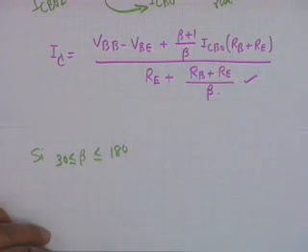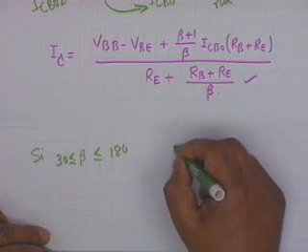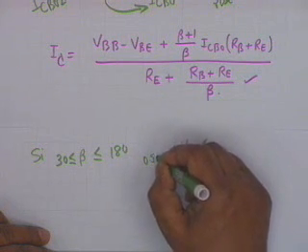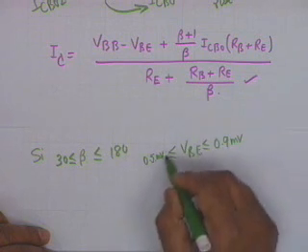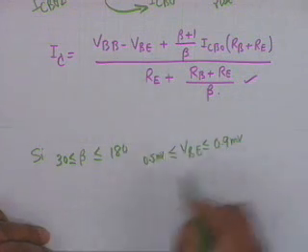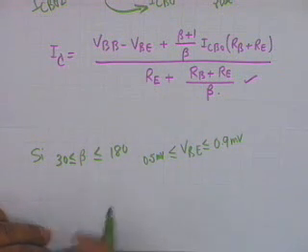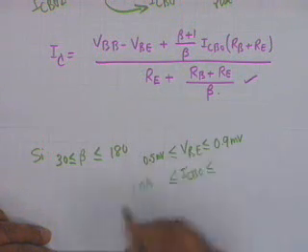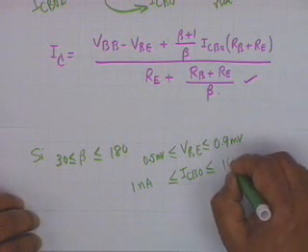VBE, the temperature is such that VBE varies between 0.5 and let us say 0.9 volt. It's a silicon transistor, but with temperature VBE can vary between 0.5 and 0.9. And I sub CBO can vary between, let us say, 1 nanoampere, nano is 10 to the minus 9, to let us say 10 nanoamperes, as much as 1:10.